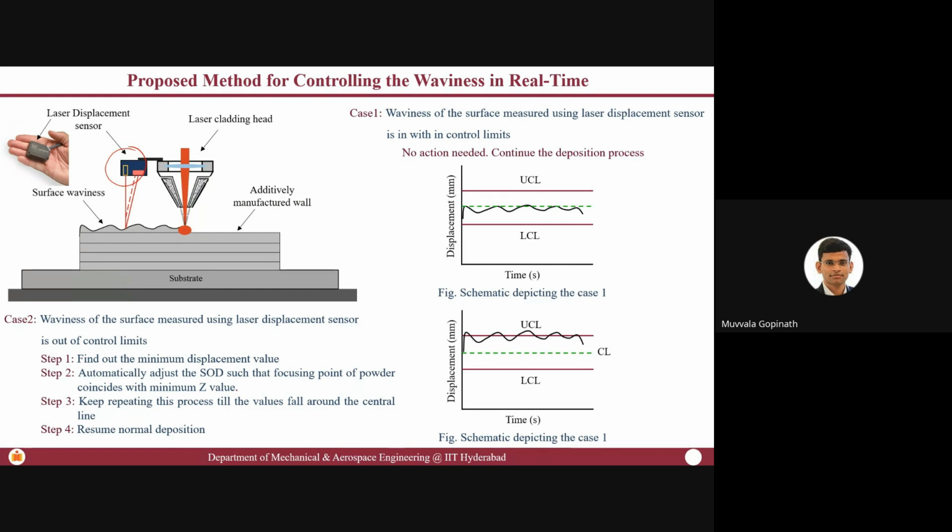So it takes from 0 to 1000 mm per minute, and it reaches that over a period of time which may be a few milliseconds, say 2-3 milliseconds. But in these 2-3 milliseconds, your deposition is going on, which is going to give an additional deposition at the start, as well as at the end when it tries to take a turn. First, it has to decelerate, reach velocity 0, and then again accelerate while returning to reach the set velocity. So this acceleration and deceleration will actually create an additional deposition there.